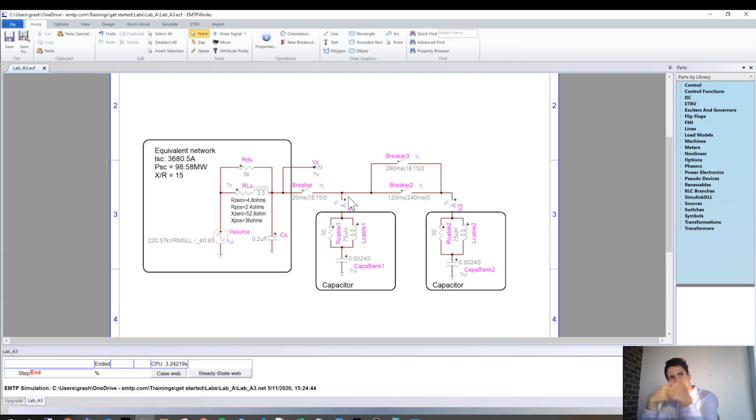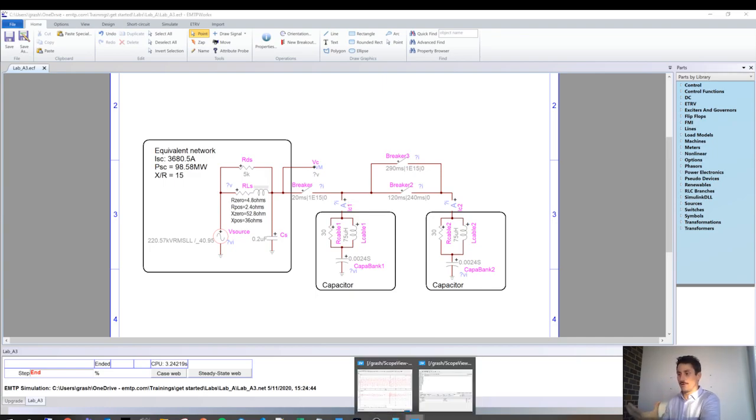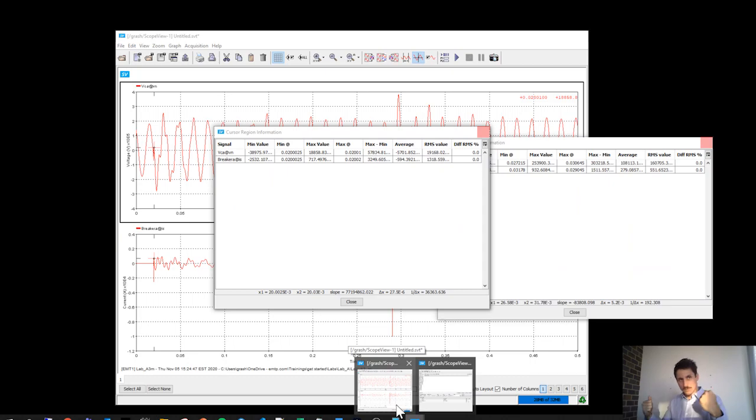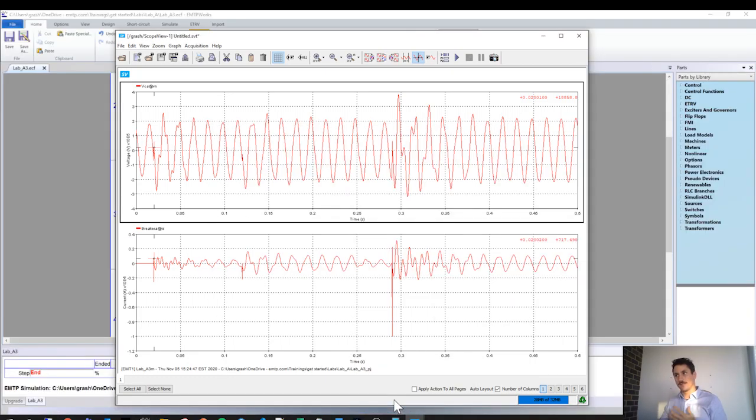The breaker will end up being completely open, and this higher transient will be interrupted at the next zero crossing. But because the magnitude of this transient is much higher, it's very possible when the current is cut that the voltage trapped is even higher. And so you may have like that an escalation of voltage. So that's what we see here. The voltage is interrupted here.